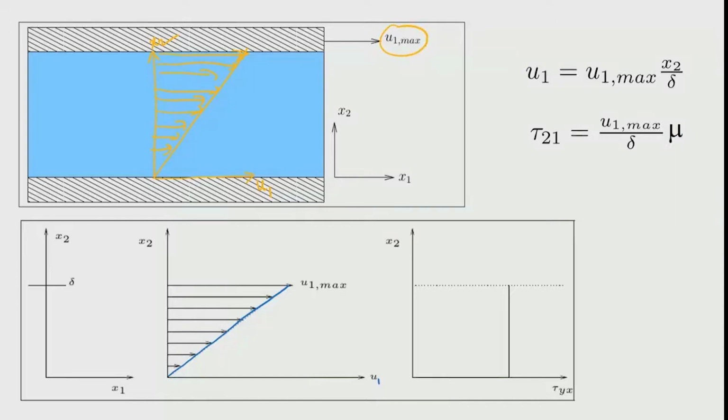And we can also see that the Newton's law we have retrieved, because when we now see that the shear stress is calculated as per the same formula, then it comes out to be a constant, and we can see that here it comes as a constant because u1 is constant and delta is in the denominator, and u1 is positive because it is along the direction of x1. So, which means that tau 21 is positive and it is constant. So, that is why the plot of tau with respect to x2 is just a constant line, vertical line, that is going like this.